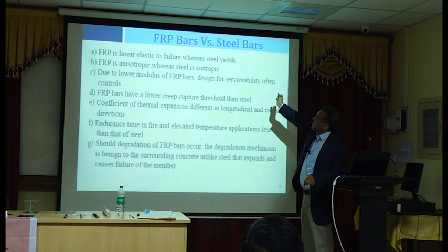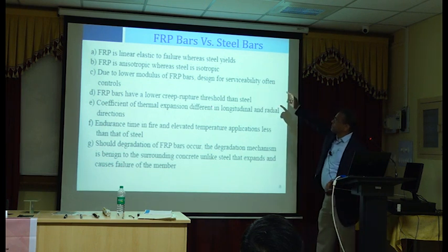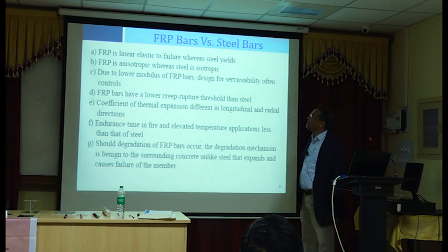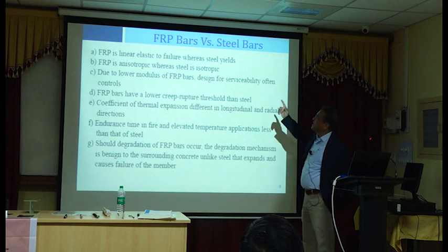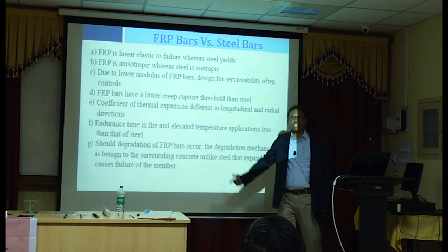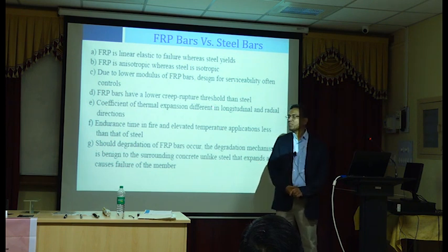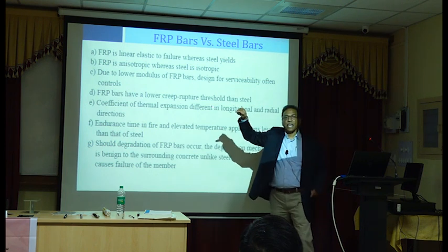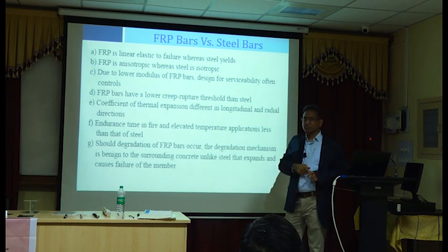And then steel versus FRP. We have already mentioned this many times. Linear elastic behavior all the way to failure, which is a problem. It's quite likely that deflections will govern your design. Deflections, crack widths are not a problem, but still, the serviceability limit state is likely to govern your design, which is a problem.